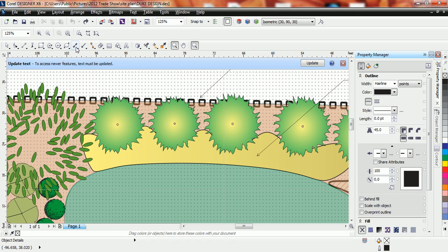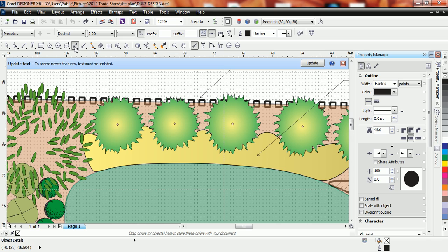So let's go back to our dimension tool. And you'll see when you select your dimension tool, as well as when you cursor over that button, the cursor flag appears, visually letting you know what tool you've selected. Your horizontal toolbar also does change. So we see here that our dimension tool will provide us a readout as a decimal, and we can also make the change where we want this readout to be to the whole number versus the tenths or the hundredths for your decimal placement. So we're going to have our dimension tool read out to the whole numbers.